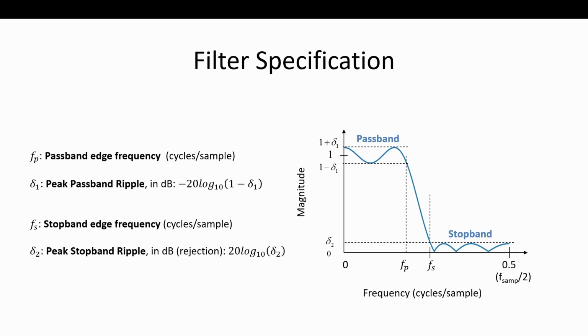You'll see the frequency axis go from 0 to 0.5, with 0 representing DC and 0.5 representing Fs/2, half the sampling rate. And that's the first Nyquist zone. That would be for the case of a real filter, where we're showing just one side, right?